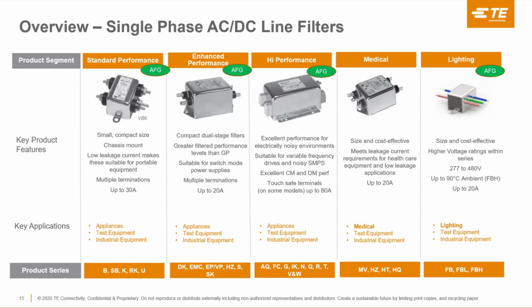We do have medical filters in here as well. They meet the leakage current requirements for healthcare equipment and low leakage applications. So it's labeled here as medical, but if it suits an industrial test equipment and allows them to pass the conducted emissions test, don't assume it's just for medical. It could be used in other applications as well. It's just designed towards the medical standards.